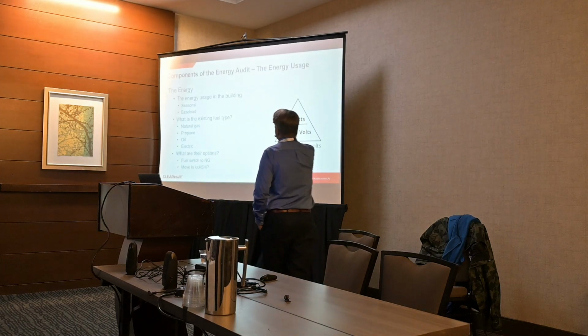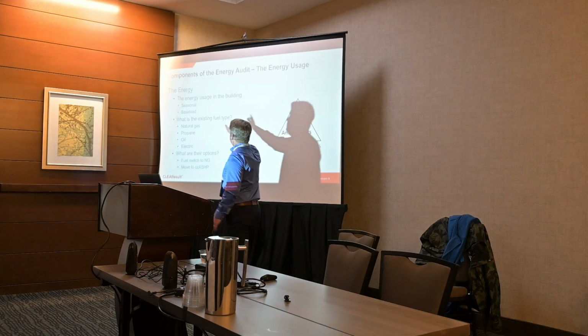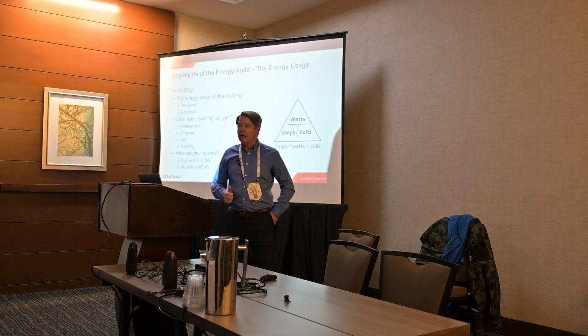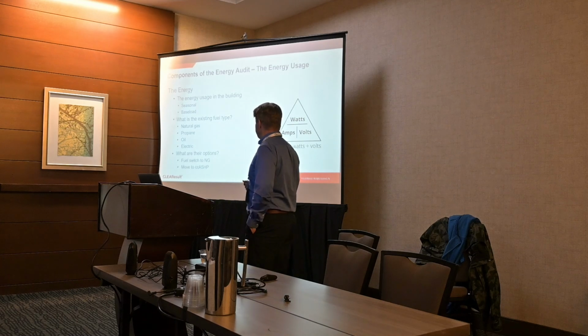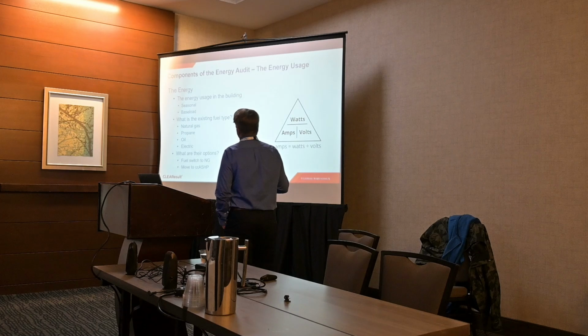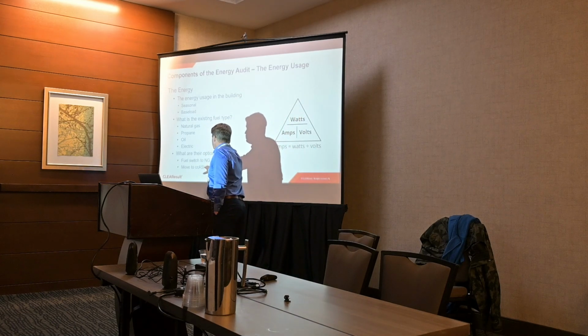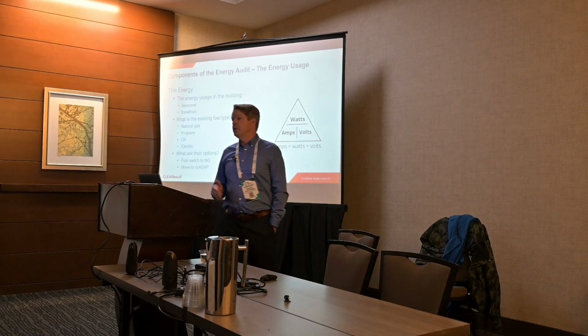Okay, we want to look at the energy usage. Like I said, separate seasonal from base load. What's their existing fuel type? Because that has a lot to do with whether or not something is going to actually pan out from a cost-effective point of view, and also from a climate change point of view. And then we can look at what their options are. Fuel switching to natural gas or moving to a cold climate air source heat pump. Obviously, today we're talking about going to a cold climate air source heat pump, right?